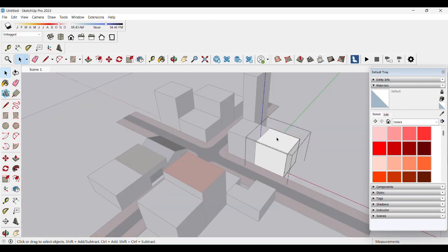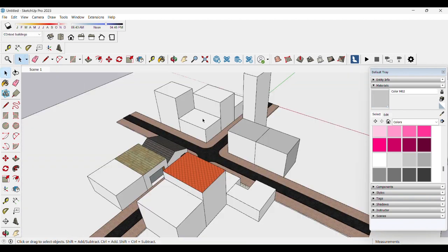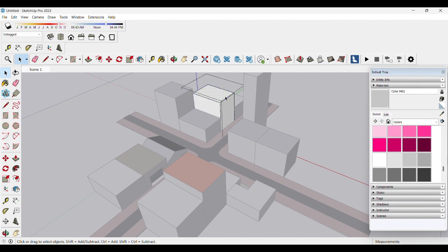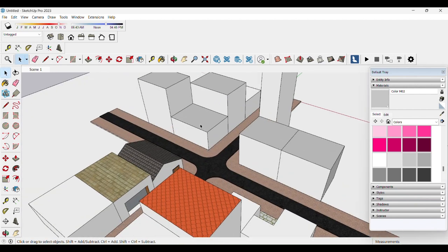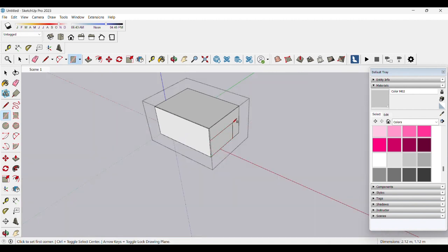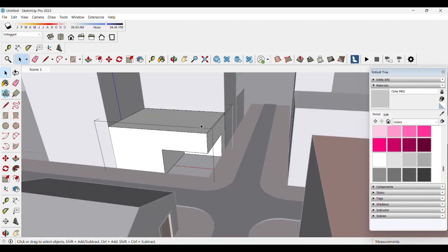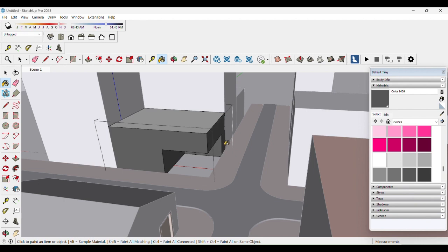Now let's give all the blocks and roofs material so that we can give the right textures in Lumion. Let's keep everything in a pastel or a lighter color. You can give any random color accordingly because that's not the final texture that it would look like. So that's just differentiating the color palette in Lumion. Anything you select gray will change together in Lumion. That's why we're giving different materials. Let's create another opening here. Click onto the block, get the surface, make it dark and contrasting.